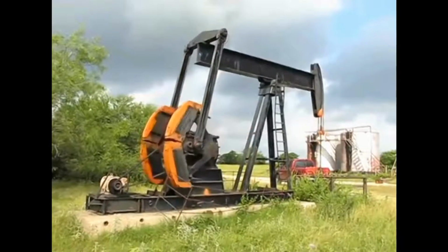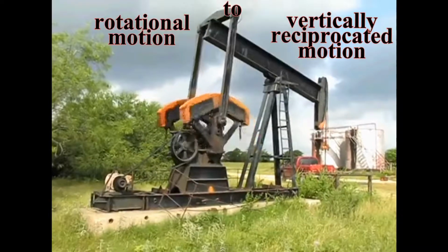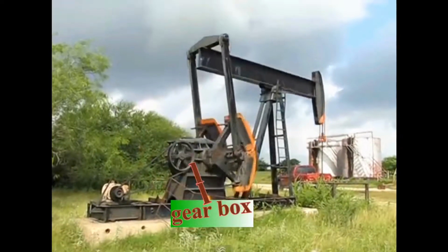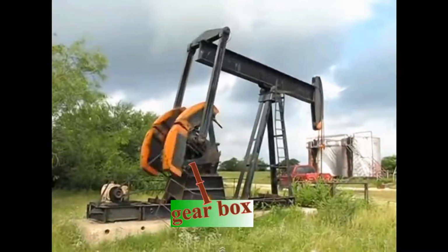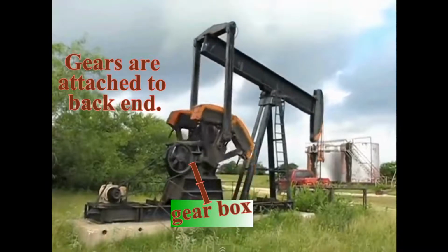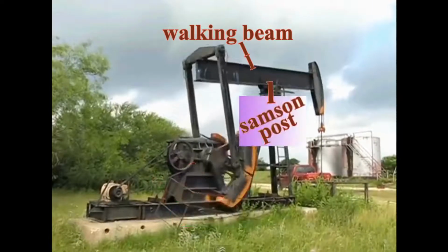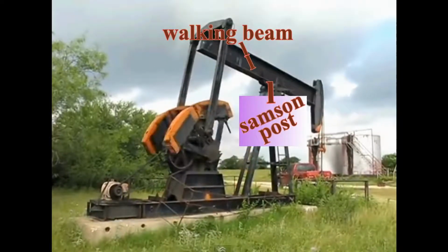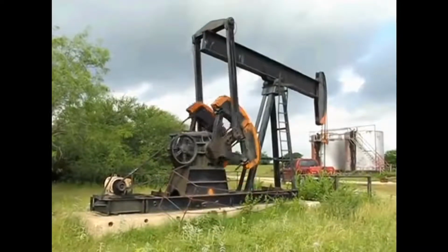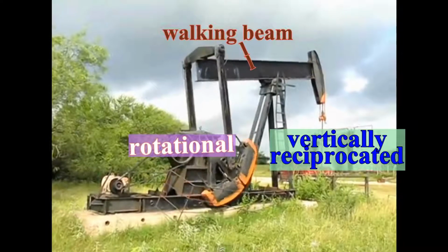For a sucker rod pumping system to work, this rotational motion from the prime mover must be transformed into a vertically reciprocated motion. This transformation is performed by the gears in the gearbox that is located here. These gears are attached to the back end of the walking beam located here. The walking beam pivots on the Samson post. As you can see, instead of going around and around in a rotational motion like the prime mover, the walking beam with the horse head attached goes up and down in a vertically reciprocated motion.